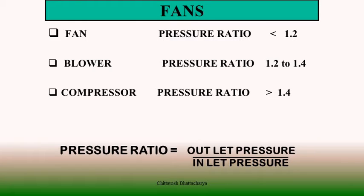It is actually a ratio of outlet pressure and inlet pressure of the gaseous fluid they are transferring. And naturally for fan, pressure ratio is less than 1.2, for blower it is within 1.2 to 1.4, and for compressor the pressure ratio is more than 1.4.